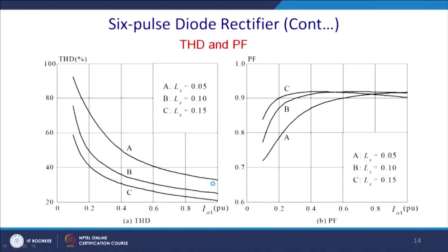Also we wanted to check a few aspects of this. This is the effect of the THD. Source inductance, you know the effect of the source inductance: you will have an overlapping region in the line current, and thus no power will be supplied during that region, that is that angle mu.